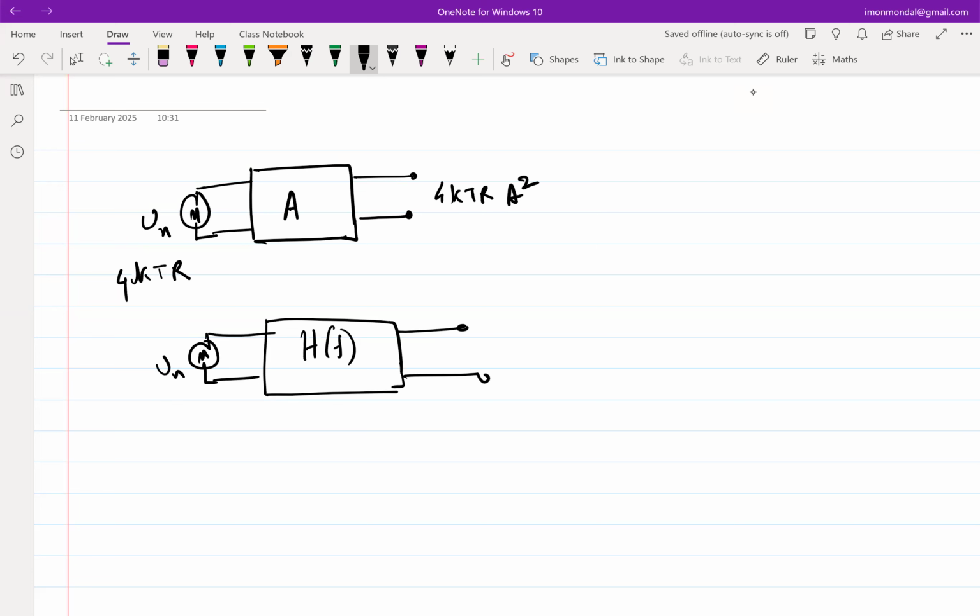So which essentially means that phase information is not there when you are observing noise. Because ultimately what you are doing, in a way, is thinking that you are observing it at a certain instant of time and doing multiple experiments and adding the power of all the experiments together, right? We are, inherently in that averaging, getting rid of that phase information, because the experiment that you are doing now and the experiment you are doing after this, there is no correlation between the data. You have it here or there.